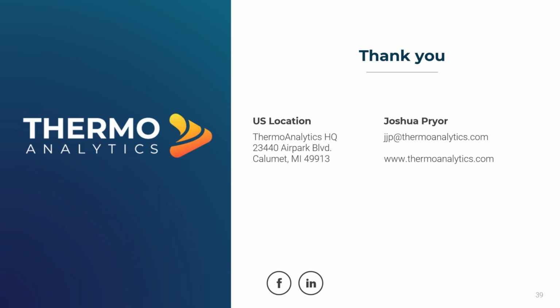All right, thank you. What was the runtime of the optimized transient run using the surrogate model? We didn't mention too much about the hardware details, but for that optimization case that was just running the surrogate, we no longer need a cluster since we're not running the CFD model anymore. So we set that up to run on a workstation with 8 cores. With the way the optimizer was set up, we're doing about 30 different optimization cycles, and in each cycle we allow the optimizer to try about 75 different iterations to find the best, just to give some context.